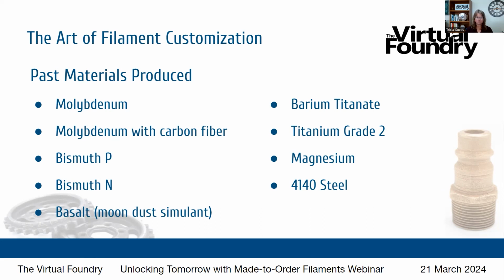Now, when you get into the different alloys, like talking about, for example, a copper aluminum or something like that, there's a couple different ways to approach it. You can either pre-alloy the material, so you wind up with essentially melting those two materials together and then making it into a powder. You can also do the alloying at the time of sintering. So you're essentially just blending copper powder and, for example, aluminum powder. And aluminum, as we mentioned earlier, has its own specific challenges, and they're all related to the oxide layer that coats each of the particles.